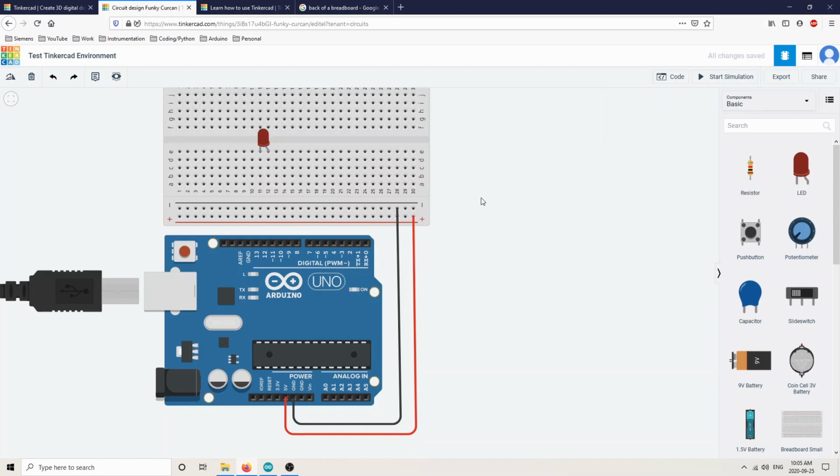Okay, just like the previous video, we needed to have a current limiting resistor, and let's bring that bad boy in there. And I want to go from the cathode, and I want to connect the cathode up to the negative. So you can see here that my resistor is now in line with the negative bus now. And this one right here now has continuity with my cathode. Okay, now I just arbitrarily decided to put my resistor as the final portion of the circuit, but I could have just as well put it here in the anode portion, right? It's a series circuit, so whichever side of the LED it is on, it's going to limit the current there.